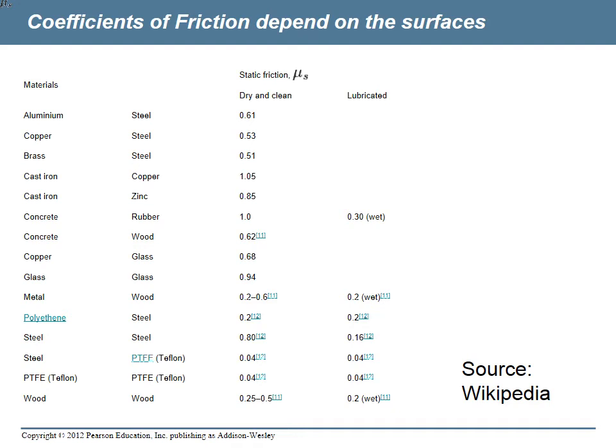But what happens when it rains? Well, it gets lubricated with the rain, and so the coefficient of static friction reduces down from 100% to 30%, down to 0.3. So now it would only take less than a third of the weight of your car in order to slide it off. That's why you slide more when it's wet out. And then if you put some oil on the roadway as well, then it reduces even more.